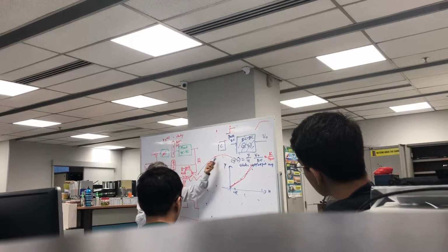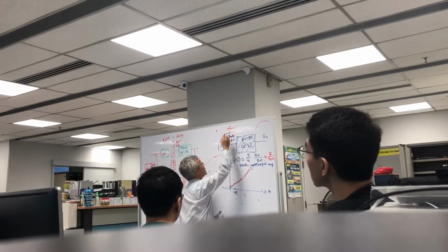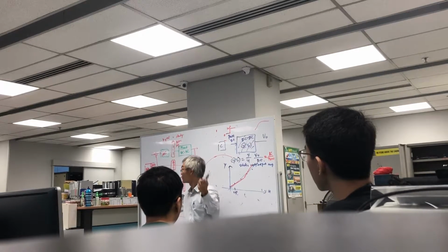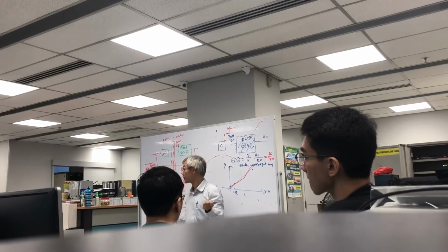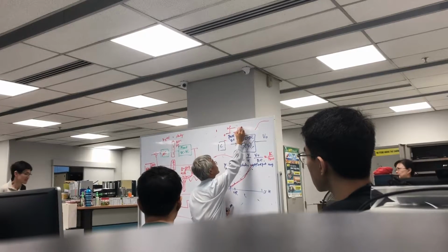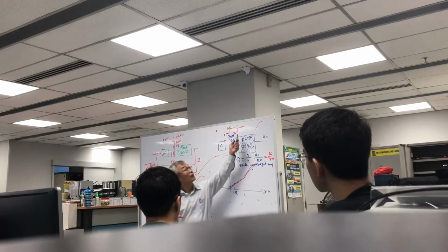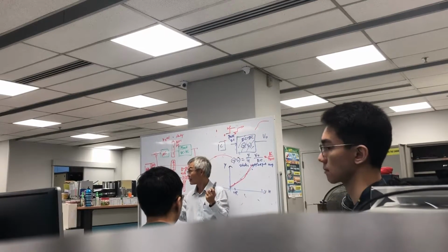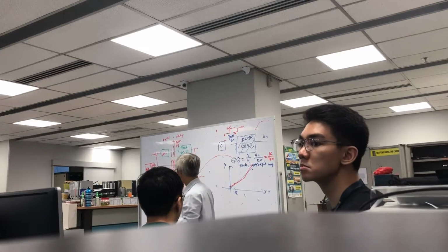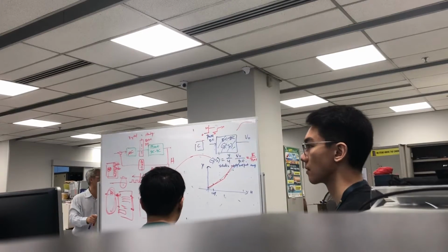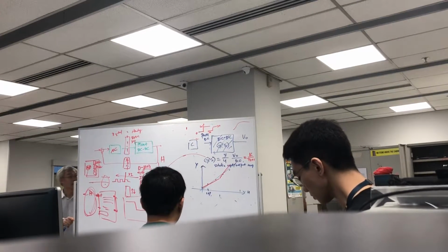Okay? So if you do a step test from 0 to 100%, most likely you will see it doesn't look like a first order response. But if you do it from maybe 10% to 20% or even 15%, you'll most likely see a linear response. So I want you to think about these kind of issues, and then for your open loop test, do these kind of things.